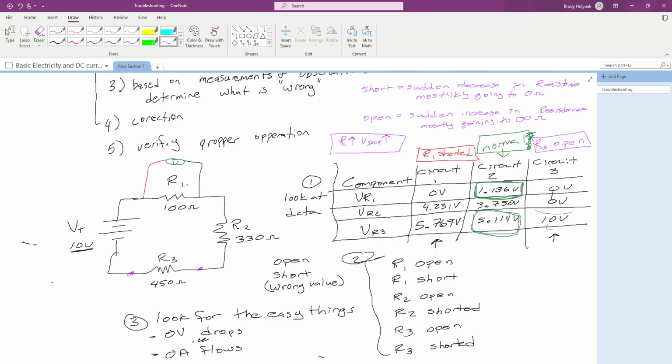If I don't have a full understanding of how a circuit board is working, I have a tool that has multiple circuits on it. All of a sudden, I start slapping in meters and things like that. I can start eliminating. Well, I know if I put 5 volts into this board, I should get 25 out of this board. I got 5 coming in, 25 coming out. Okay, that board's good. Well, then that 25 volts gets fed into this board and then gets split up. Oh, wait a minute. I'm not getting the split like I should in other areas. So my problem's probably in that board.